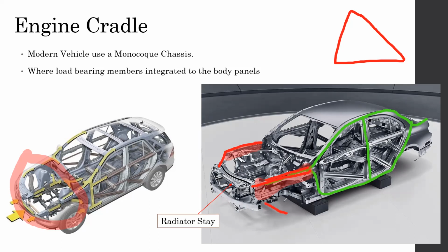That means you have a suspension, one lower arm like this, and a coil spring and strut assembly goes like this. All the loads from the road will be transferred through this suspension assembly. It will be transferred to this top mount.